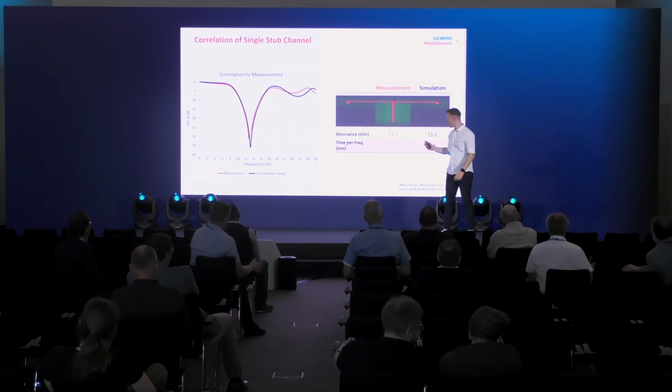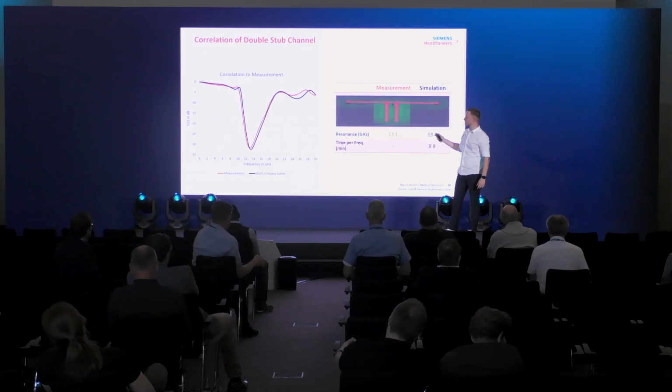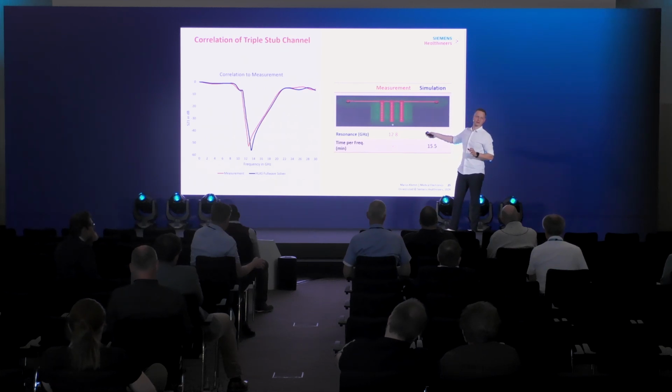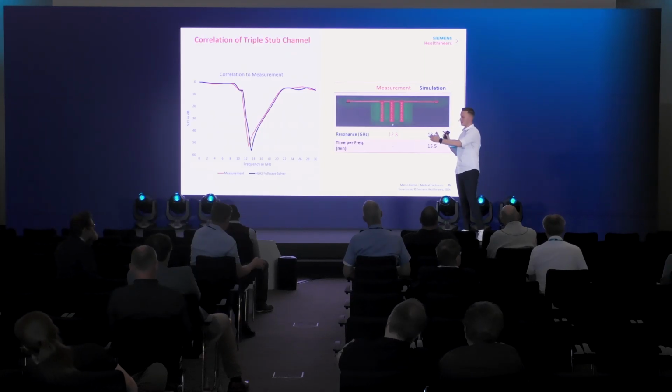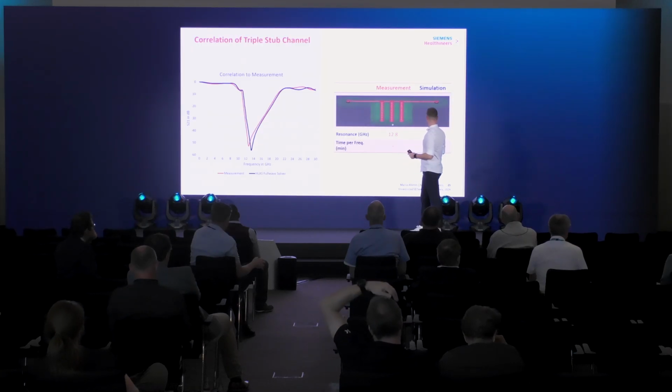For plots like this one, what I was also interested in is that I used adaptive frequency sampling, and I always simulated up to 40 gigahertz, which we don't see right here. I always had between 12 to 15 frequency points in the total range, and then got an interpolation. The maximum I simulated was about 15 points, up to 15 minutes.